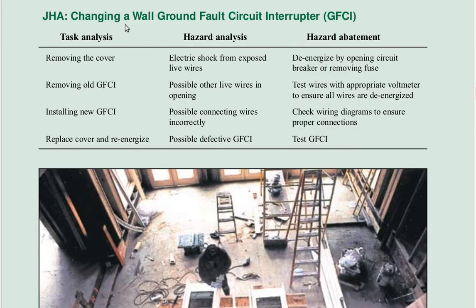Job hazard analysis: changing a wall ground fault circuit interrupter, GFCI. Task analysis. You will remove the cover. You look at what can go wrong while you remove the cover. Electric shock from exposed live wires. What to do? You must de-energize by opening the circuit breaker or removing the fuse.